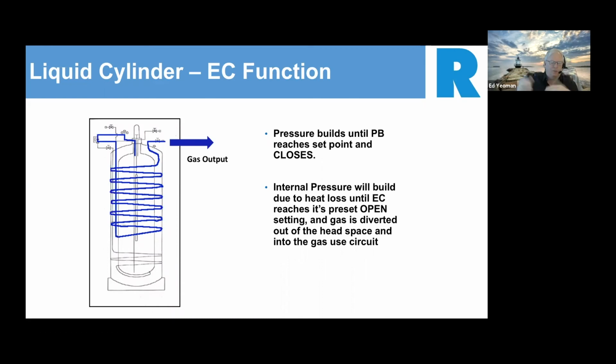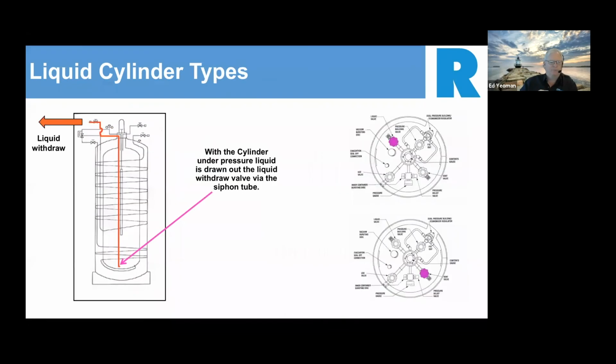Obviously, if you don't use the cylinder, you turn the pressure builder off, it'll continue to build pressure. That's when the relief valve will kick in and will help normalize the pressure in the cylinder, prevent it from overpressurization. Next slide, please, Marie.